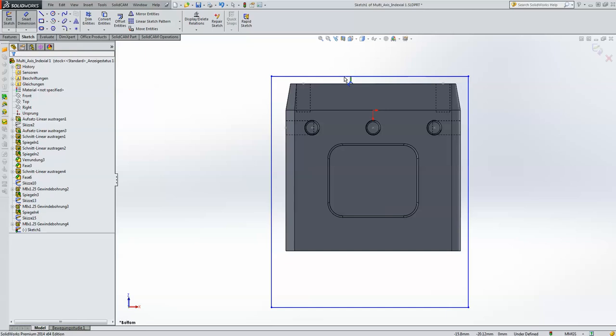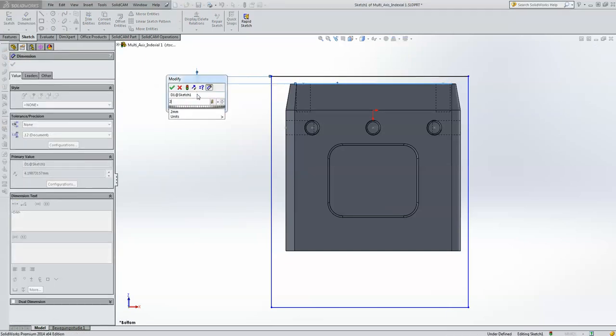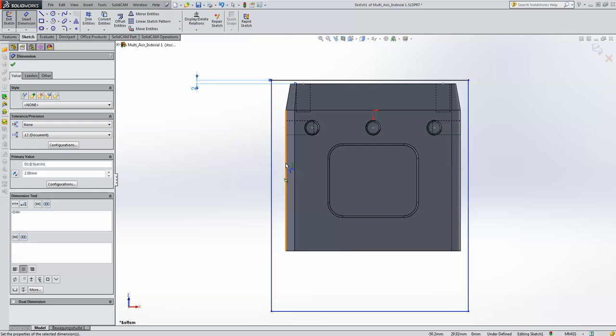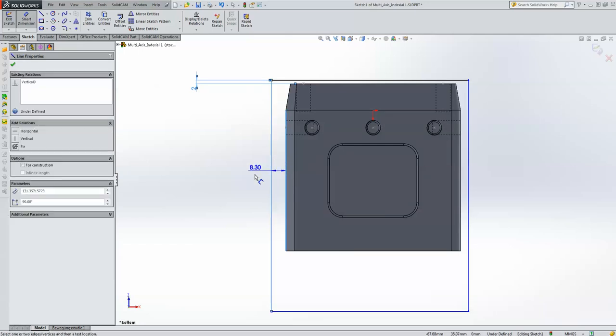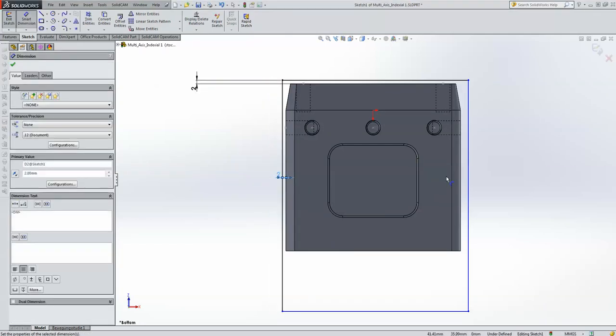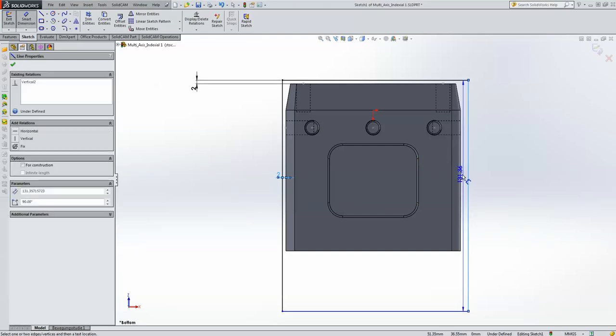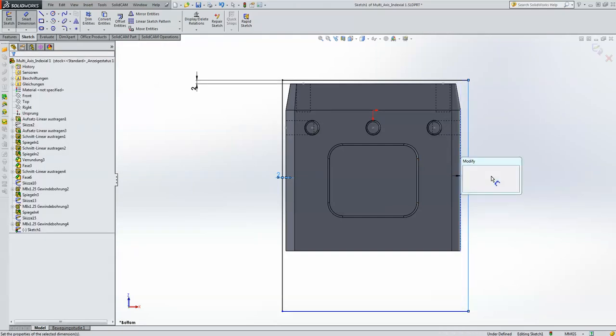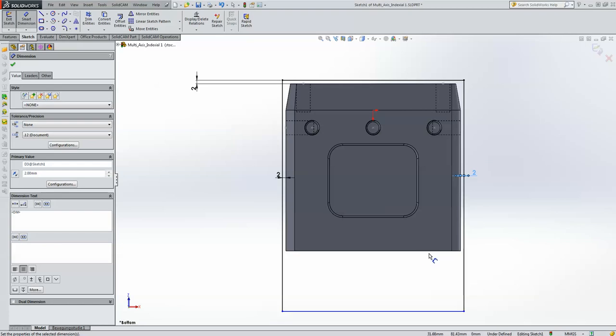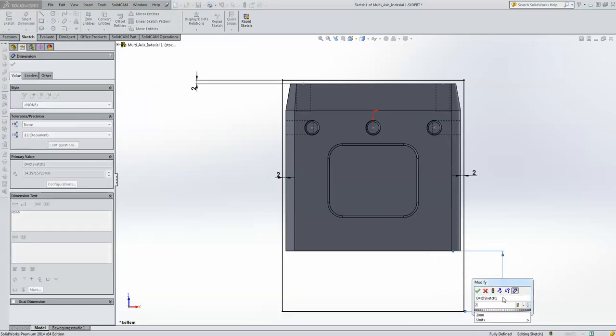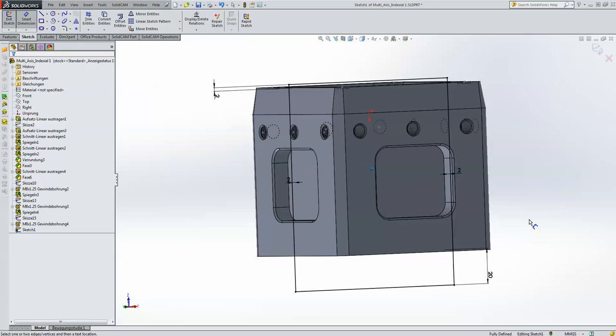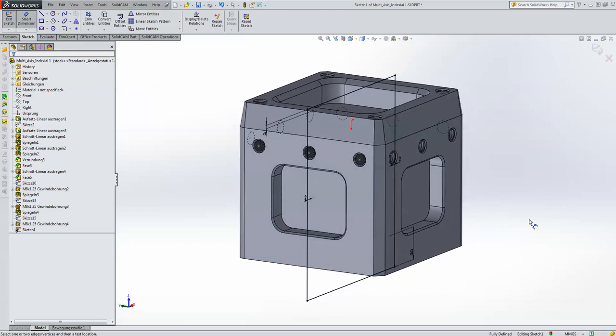My top from the top of the part to over here, I'm going to have that at 2 millimeters. I'm going to start this edge to the edge of the sketch over there, also 2 millimeters. The same thing, this edge over here to this edge over there will also be 2 millimeters. And last but not least, the very bottom from here to here, that's going to be actually 20 millimeters. That's the excess material I'm going to need at the very bottom of the stock itself. As you can see, I've created my sketch exactly in the middle of the part over here.